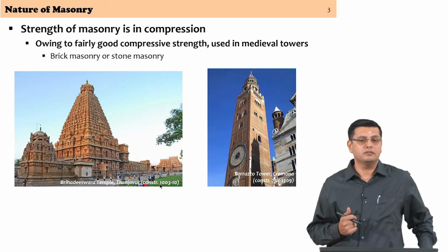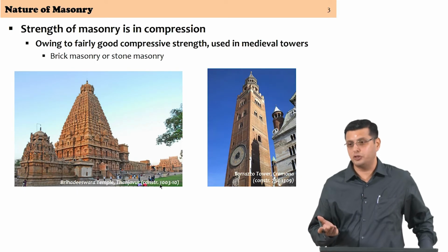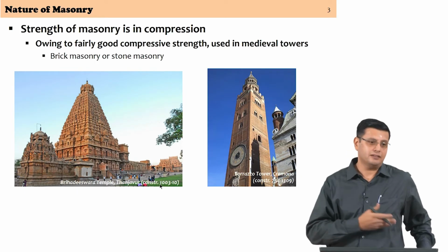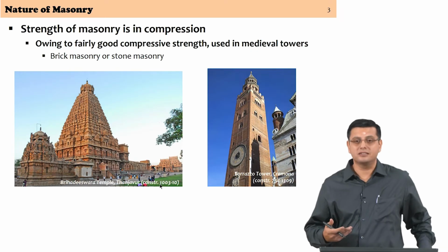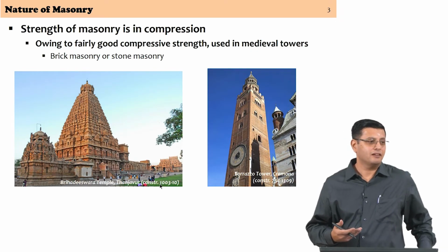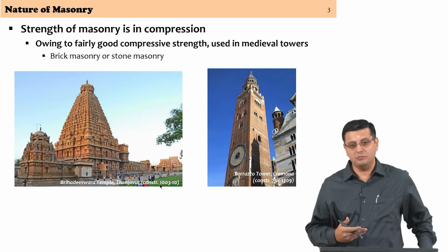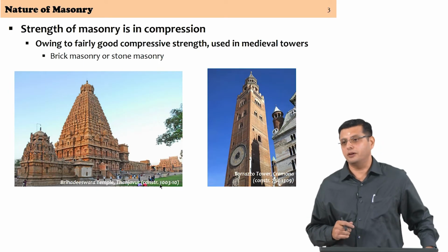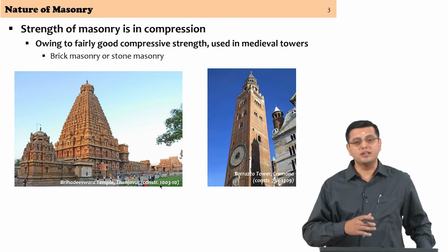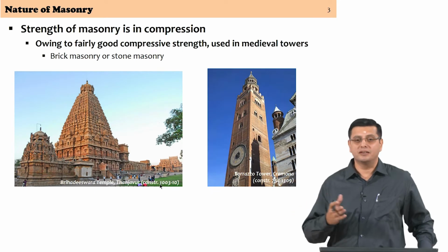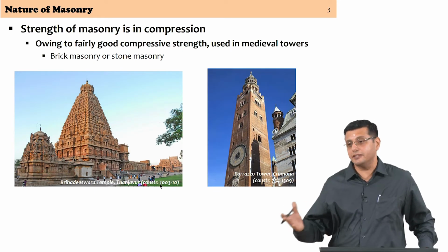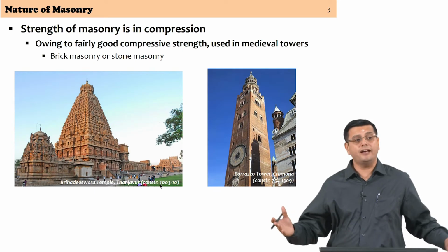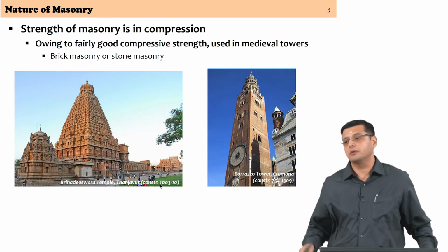Of course, there is going to be an issue of stability, and that is the reason why these towers have stopped at 100, 120 meters in height. Of course, you can improve the compressive behavior of a material by choosing the right cross section, integrating stronger materials in the cross section, and choosing a form that gives you better stability.